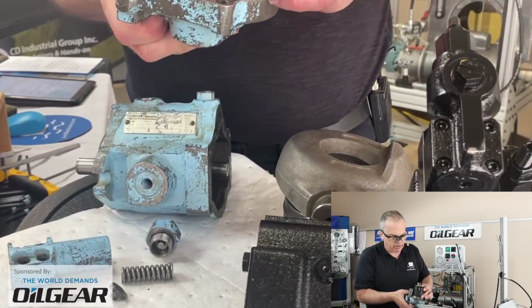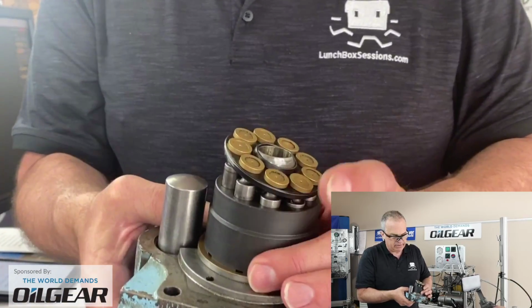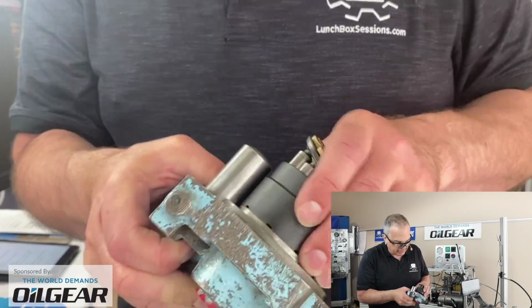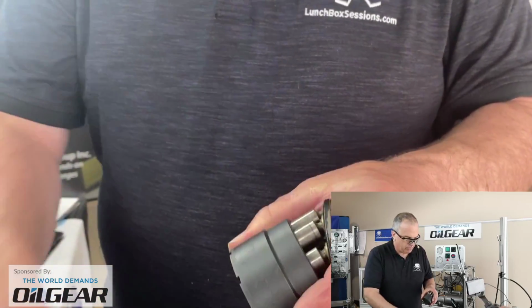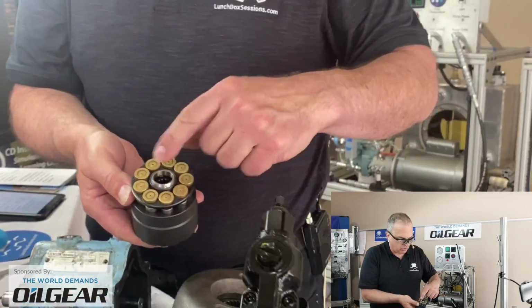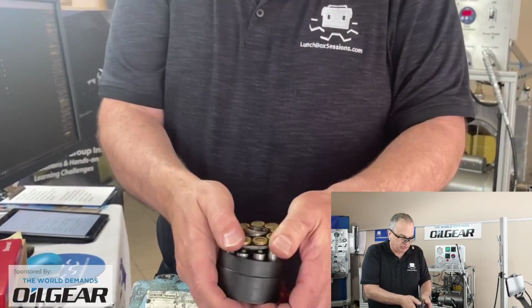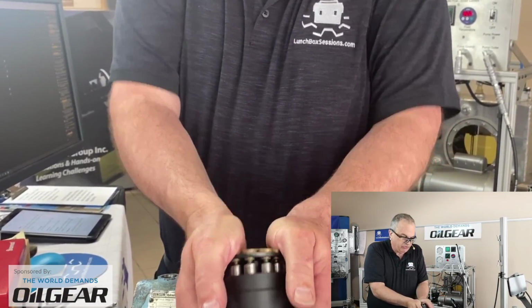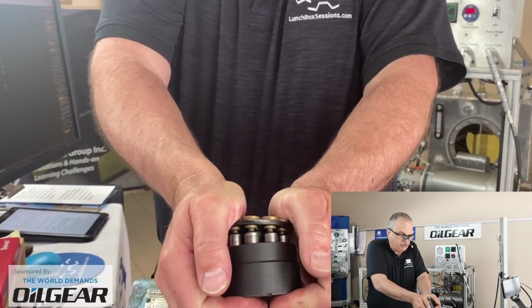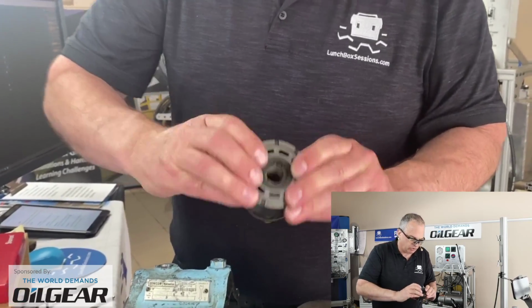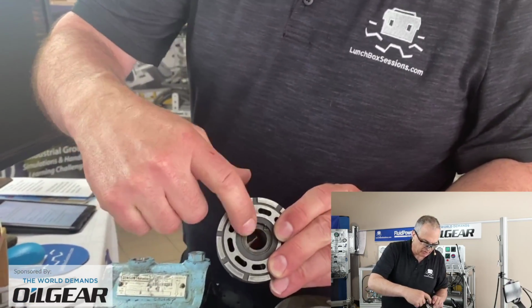The cylinder barrel, of course, is turning there. How do we prevent a lot of leakage from happening between there? What you'll notice is that underneath the spherical washer, if we look in there, there are 3 tiny little pins holding the retaining ring at a distance. If I squeeze this, you'd see there's definitely some spring action in there. There's a load spring inside the cylinder barrel.